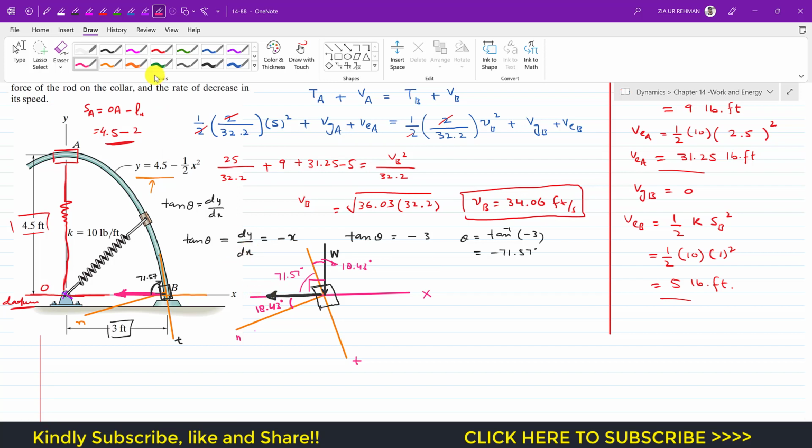This is that spring force. Let me write the spring force, and this spring force will be equal to K times SB. And we know SB is the elongation in the spring when the collar is at B. So we have determined that SB is this OB length, the stretched length, minus the unstretched length. OB is 3 and the unstretched length is 2, so this is 1. So this spring force is K, and K is 10, so 10 times SB, which is 1, so this is 10 pounds. So the spring force is 10 pounds.